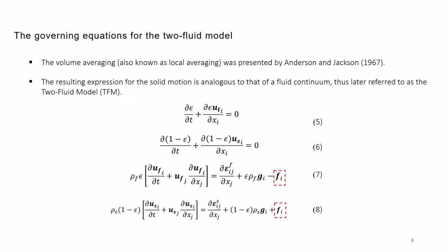And if we look at the governing equations presented by Anderson and Jackson back in 1967, we can see they consist of the volume average momentum and continuity equations, with the particle fluid interaction forces appearing on the right-hand side of the momentum equations. Such representation is analogous to two fluids interacting together, where the solid phase appears as a fluid with some sort of viscosity and density that affects its behavior.